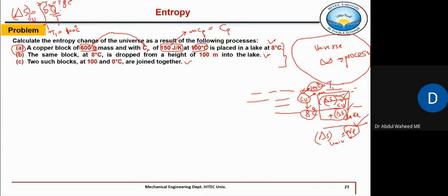Okay. So that is the equation with limits. So we have to calculate this entropy change from this initial state, 100 degrees Celsius, to final state, which is 8 degrees Celsius. That will be the entropy change of copper. Now, very important thing is equation where you see single T, it's not delta T. So ये जो temperature है, that should be in kelvins. So it is 373 Kelvin, and that is 280 Kelvin. So ये जो आपने integration perform करनी, that should be from 373 to 280 Kelvin.